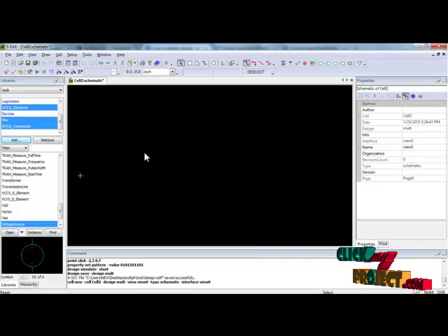After setting up the design, we have to load the library files. Initially, for CMOS designs we need some CMOS components. Those CMOS components are contained in CMOS libraries. That means CMOS libraries contain the components required for CMOS design. Here you can see the components listed in the CMOS library. While you are pressing add, it will lead you to a window menu. There you can locate the library file where you have stored it, and from that location you can select all the components you need for your CMOS design.